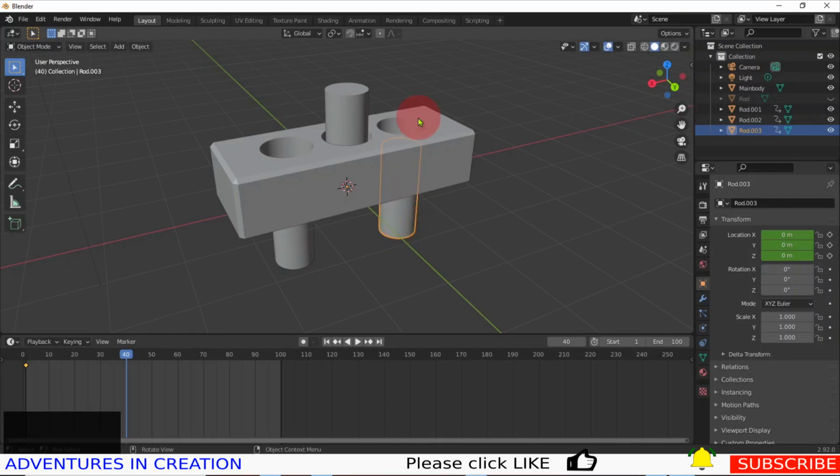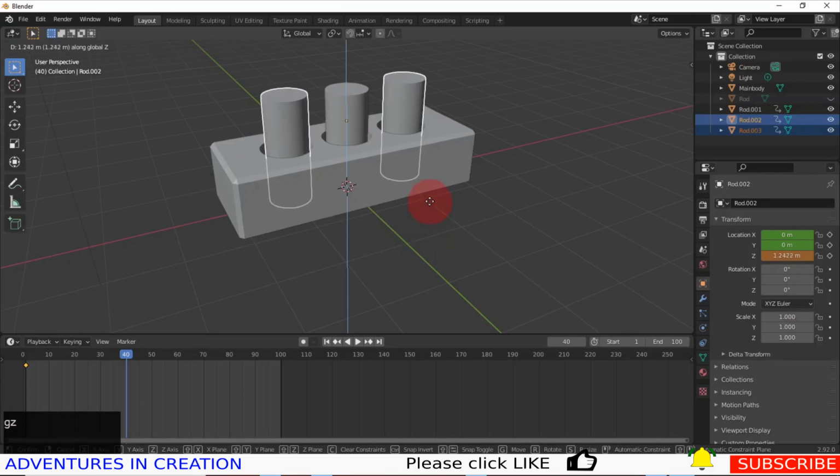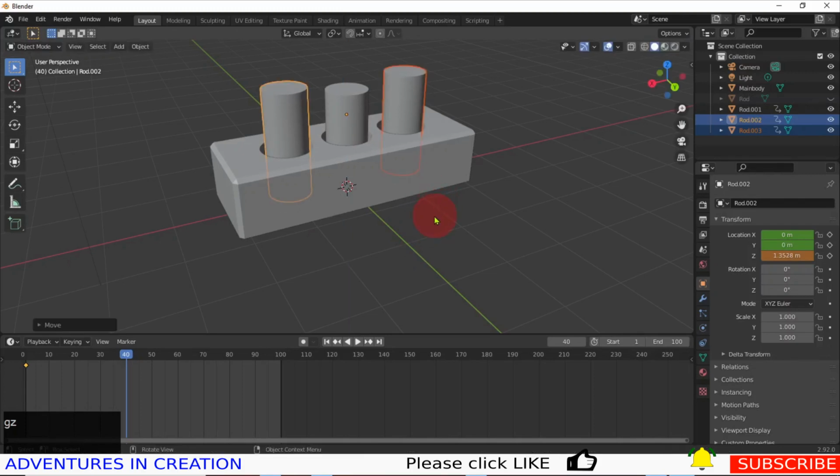I'm going to select this rod and this rod because I want them to go in unison. And I'm going to say G for grab, Z for the direction I want to go in, and I'm going to move them up to here. And just click. And now you can see the Z direction has changed. So what I'm going to do is select each rod and click the keyframe. Select the rod, click the keyframe.